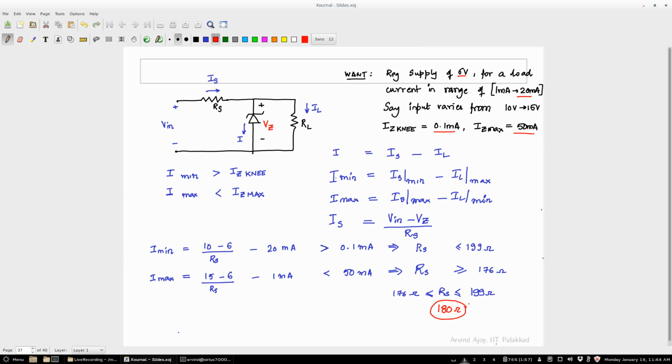And then if you're designing a fan regulator or something, the old fan regulators which are really big, those would have been like 10 watt resistors, right? Nice and thick and fat. So you can't take a quarter watt resistor and put it in an application which requires 10 watt of rating. What will happen? It will burn, right? You don't want that to happen. Fire hazard. So to specify a resistor, you need to specify its value and also its power. So what would be its power rating?